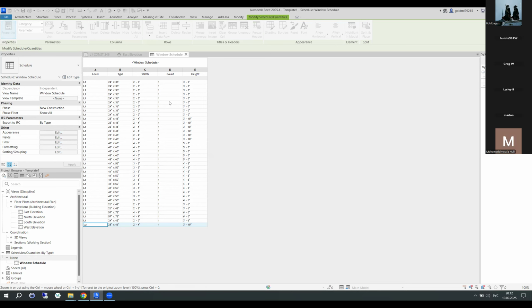Perfect. Now you can at least see what they're reporting, and you can see all those other windows that are way high and at least get a value for them so you can figure out what level they should be at, right? So now instead of them all just looking like they're at level 1 at 3 foot, that's the real sill height of them. And you've got 6 windows that are reporting 30 feet up or whatever. But you can change the level so it reassociates it.